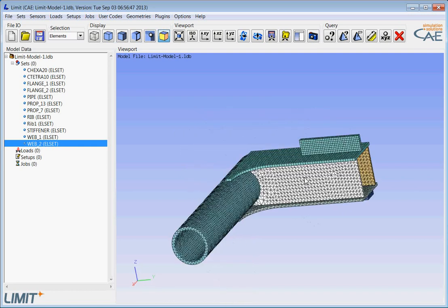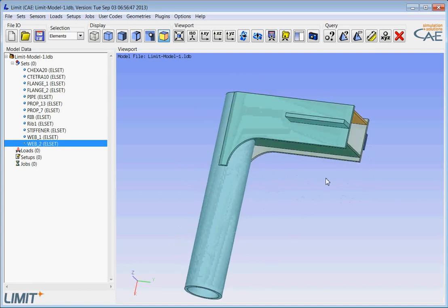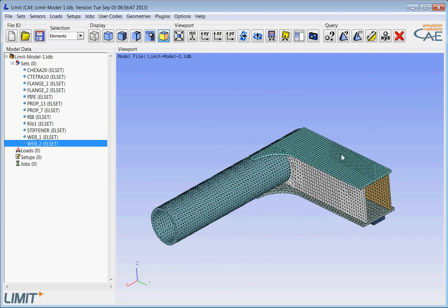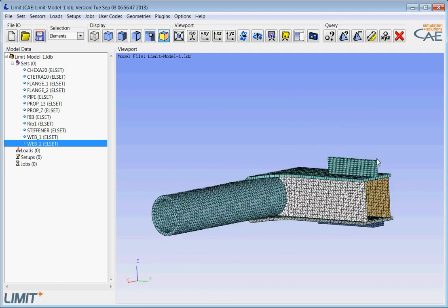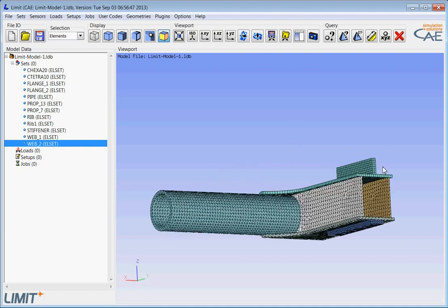One important thing is that you can only use these sensors for really thin-walled structures, and each element set or each part must have one representative thickness, which actually is the smallest distance between two parallel faces.